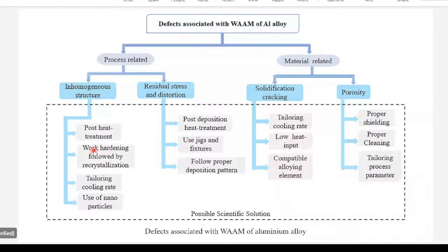The inner layer heat affected zone will also be very refined, and the microstructure will look like a continuity. So columnar grains or equiaxed grains we can attain with nanoparticles.